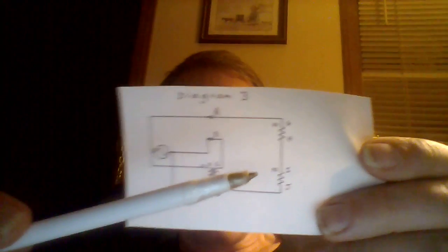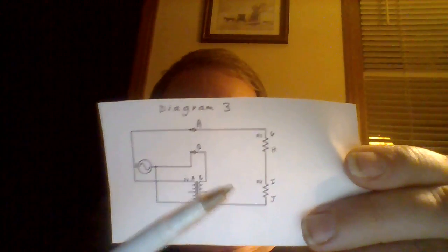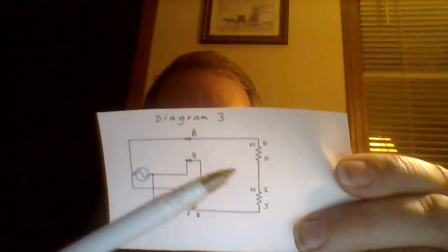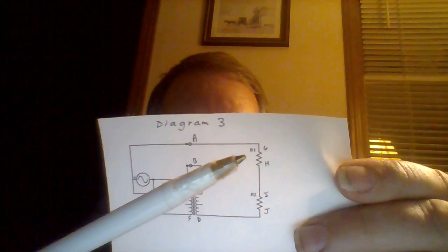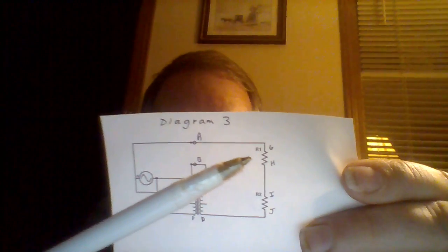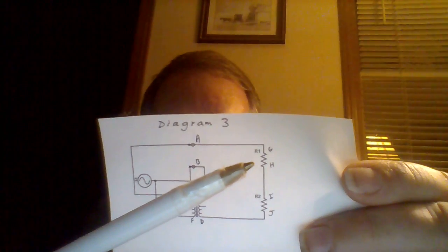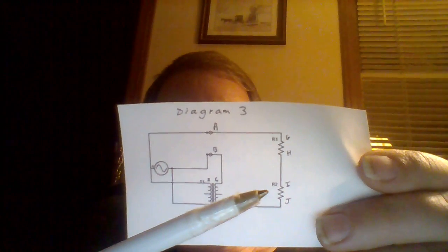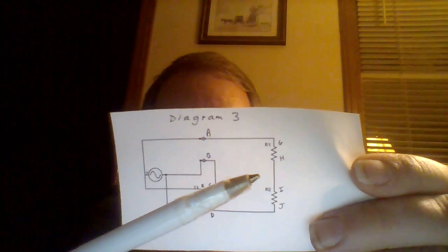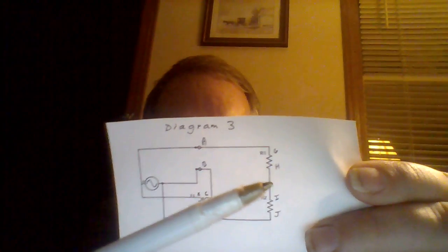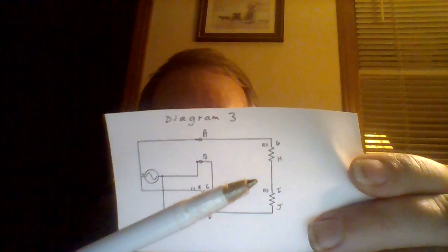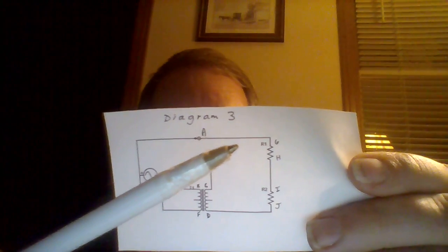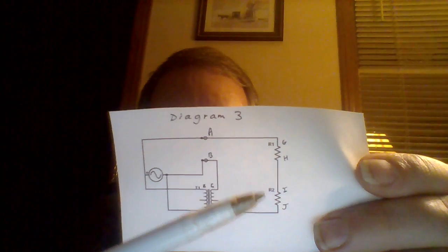Okay? But now, the fantastic thing about this process is that, from Ohm's law, for a 100-watt light bulb, the resistance measures about 144 ohms. But now we got two here. So add those together, that makes 288 ohms. So what that should do is cut the current in half. So instead of having 833 milliamps, it should be about 416 milliamps.